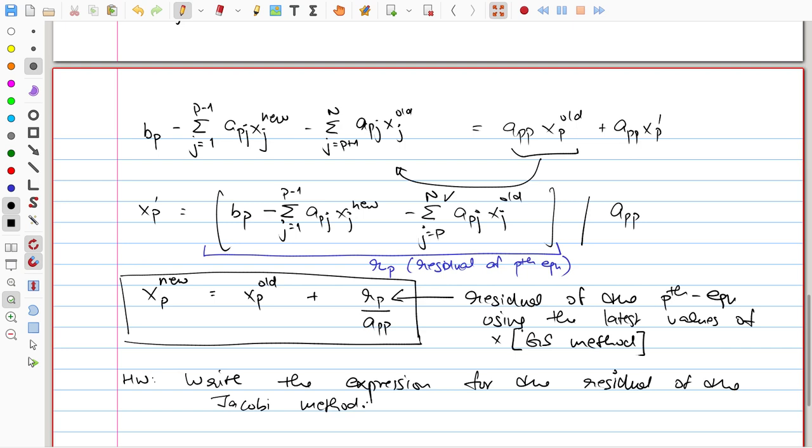There are many reasons possible. The problem is not well posed. You are implementing a non-linear problem where you're taking a very large jump between time steps and so on. So there could be many reasons. That's sort of the daily life of a CFD engineer. There's no one answer to it, but that's a question people are dealing with on a daily basis.